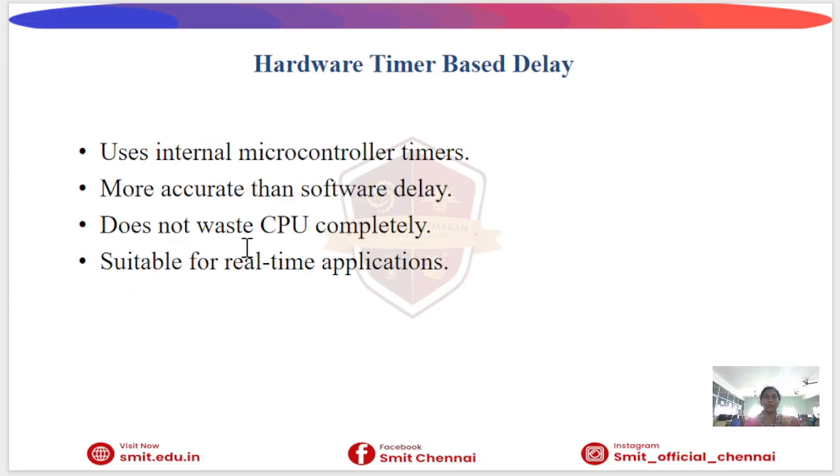Then the hardware timer based delay. This method uses the internal microcontroller timers. Microcontrollers like the 8051 have built-in timers. So instead of wasting CPU, we configure the timer register. We set the timer register and wait for the overflow flag. The overflow flag gets set on time and generates an accurate delay.